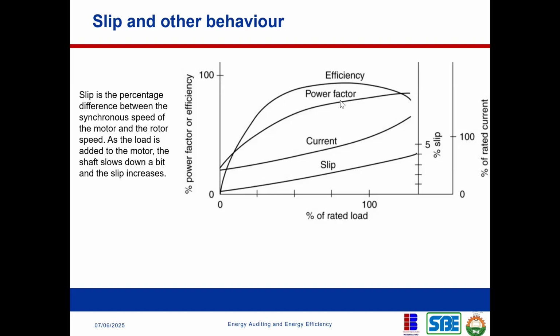Okay. And that's why when you underload your motor, your efficiency is usually low. Now this highest curve here is the efficiency. You can see that the efficiency is highest from maybe about 70 up until you get to like 100. If you load your motor above 100, you're on your own, you begin to reduce the efficiency and you also put that motor at risk, at danger. So this is just to help us understand that relationship.